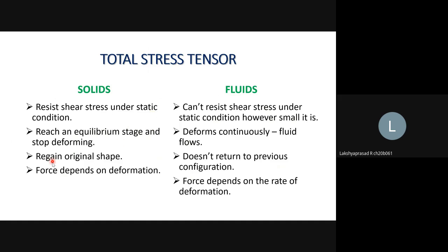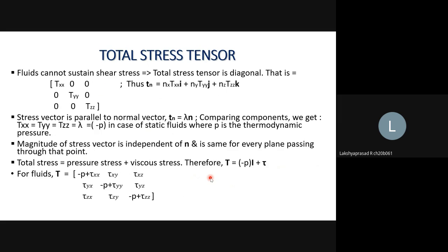Solids can regain their original shape once the force is removed. However, fluids just cannot come back to the previous configuration. For solids, the force acting upon it will depend on the deformation. However, the force on fluids would depend on the rate of deformation. These are important differences to be kept in mind. We'll move on. As we saw, fluids cannot sustain a shear stress, and thus